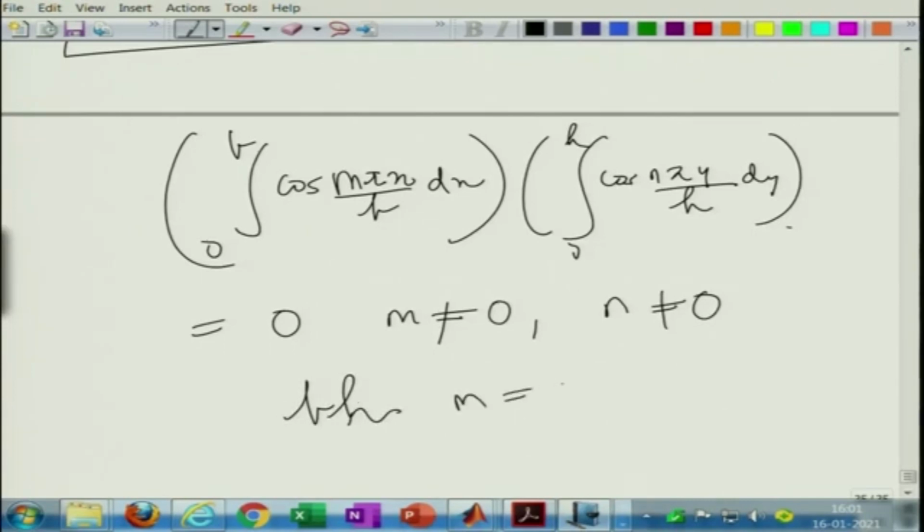What this really means is that the contribution to the mass velocity by the higher order mn modes is identically 0. That is, if you integrate the velocity contribution of the higher order modes over the cross section area, it is going to be 0. We will show eventually in later weeks of our course that this is probably one of the reasons why a plane wave is a very good approximation.